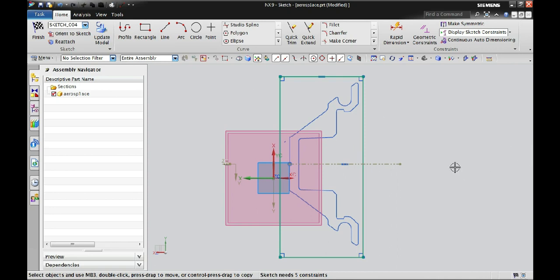Select this one as a stock. Now you want to select complete 3D modeling. With this as a center line, you will be revolving the top layout sketch to get a 3D model. If you look at my previous videos, they clearly explain step by step the part modeling, toolpath selection, selecting the tools, and applying the toolpath for the mill turn.